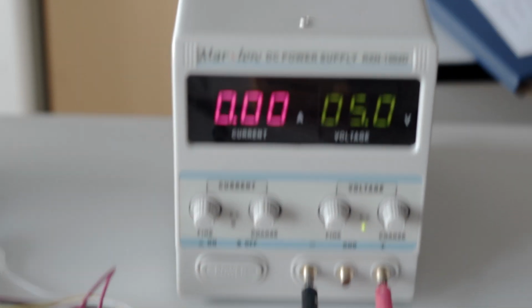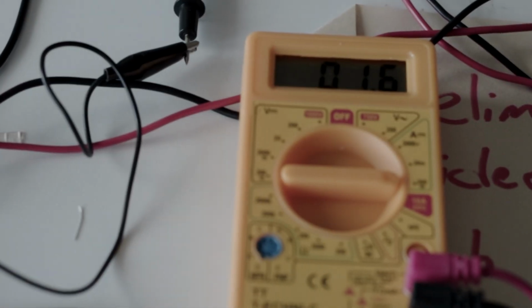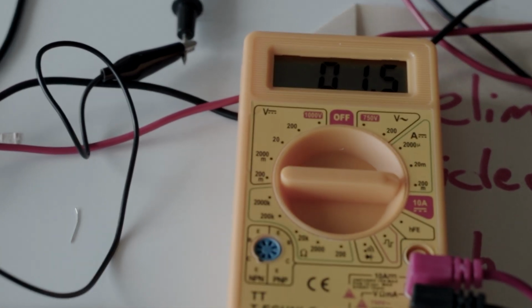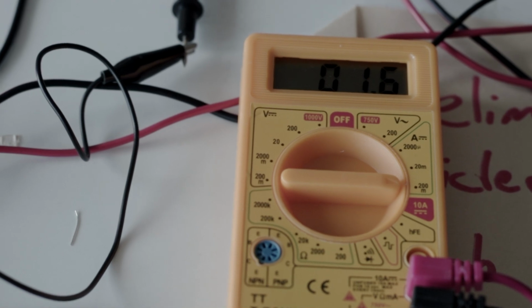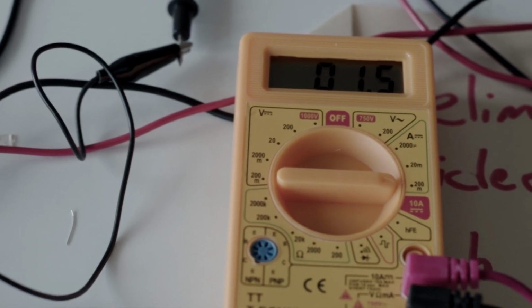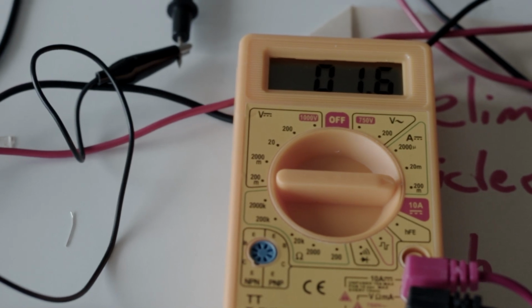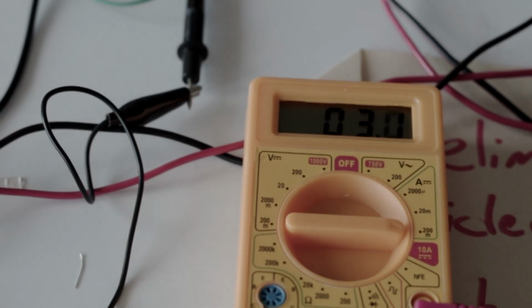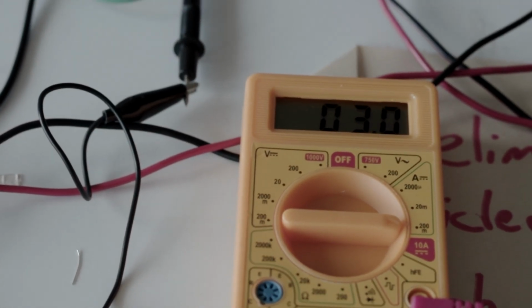You can then see that the multimeter in ampere meter mode gives us 1.5 milliamps, even 1.6 milliamps, which is what we expect for the current through R1. Of course, you can increase the resolution, for instance, by building this circuit with smaller resistance values, such as 330 ohms. Or another thing you can do is just increase the voltage to 10 volts. You can select 3.1 volts, etc.